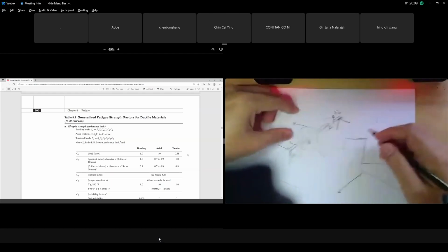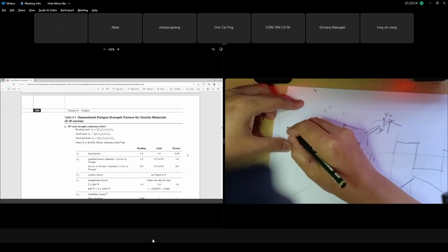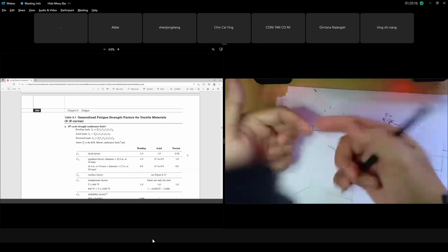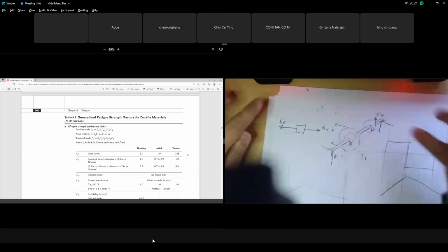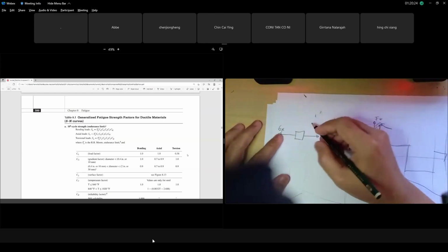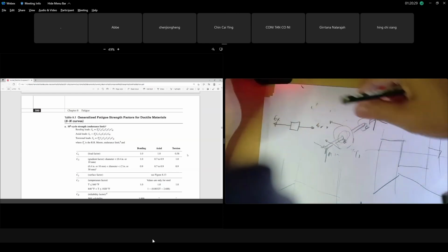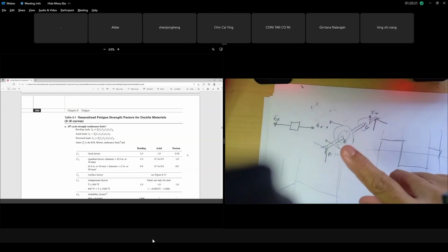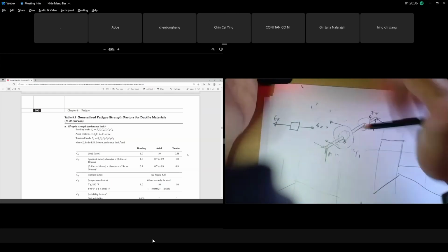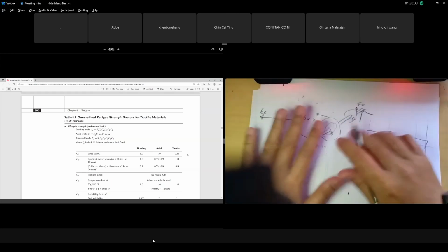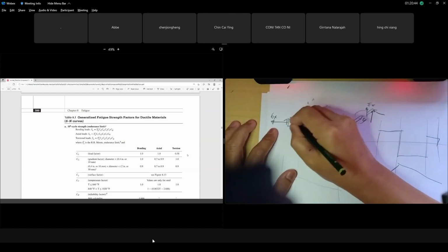At B, remember, when you look at an element at B, you have sigma X, right? Sigma X, do not confuse, this is not axial. This is sigma X based on bending, guys. Do not confuse. The sigma is based on your bending. But we don't have axial loading. Remember when you did NLC, we also had sigma axial in the case of the rod, the one in your assignment, remember your rod? At point A, the rod AB. That is the one where we have axial. But in this case, like the shaft, for example, we don't have axial. In this case, the shaft, but we have torsion, right? Torsion, torque XY here, torque XY there.